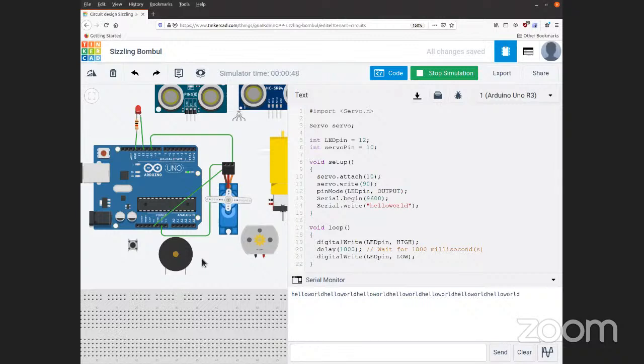So if you're doing some funky programming so that you're not using the high or low keyword, but you're using some variable and you're not actually sure what the status of that pin is, you can actually read it out, put it to the serial monitor, and that would be like a digitalRead of the LED pin. You could just Serial.write the digitalRead of the LED pin, and that would give you the current state of it. So things like that.